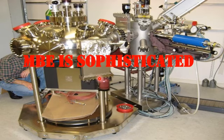Another sophistication with molecular beam epitaxy is that this technique is attached with other techniques like electron beam evaporation, which is used to evaporate the precursor inside the molecular beam epitaxy reaction chamber. It is also connected with effusion cells, which are present in the reaction chamber, and inside the effusion cell the dopants are kept and evaporated. So the effusion cell is also another type of system.